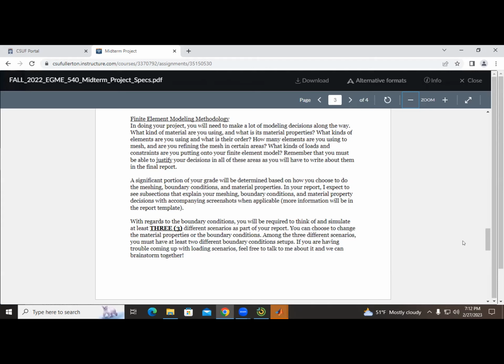You mentioned that a lot of other engineers are going to be questioning FEA. When you say that, are they questioning the FEA method itself, or the way you did the FEA? It's the way that you did the FEA. Oh, I see. Thank you. Yeah, because there are a lot of ways that you can do FEA, and you saw it in the last activity. Even something simple like the element shape, tetrahedrons versus hexahedrons. We know there are trade-offs between the two, but you can kind of make it work with both.